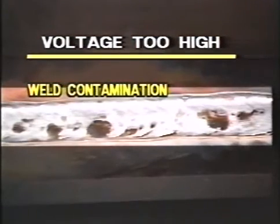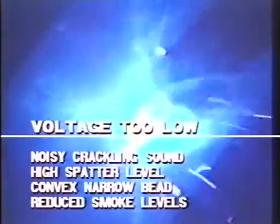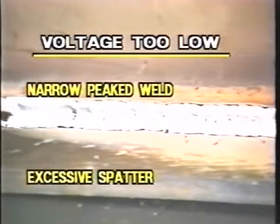Weld bead width increases as voltage increases, resulting in lower penetration. A longer arc length increases the chances of the weld droplet, as it is traveling across the arc gap, picking up contaminants from the atmosphere. A noisy crackling arc sound is the result of low voltage. With low voltage, the wire is driven into the weld, disturbing the puddle, causing spatter. The weld bead will be narrow and convex in shape. Smoke levels will be reduced as the voltage is decreased. Notice the decrease in bead width and resultant increase in spatter. Let's have a look at a spray transfer.